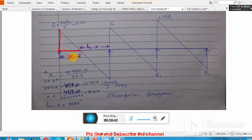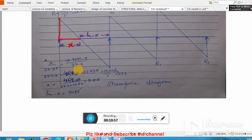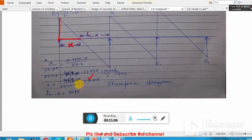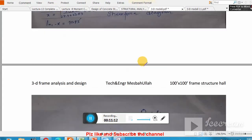Using the similar triangle rule, x divided by that ordinate, that is 23.83. WU is determined, and we know ln1, so divided by 2, you get this one. Simplifying this equation, you get x equal to 8.80. So this x, from the face of the support, is 8.804. Clear? And the remaining distance will be 10.13. This is very important.